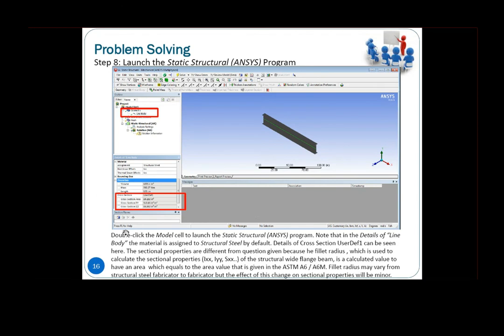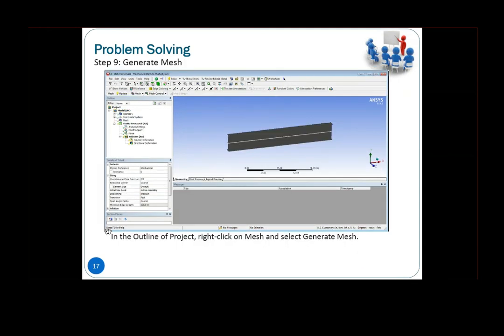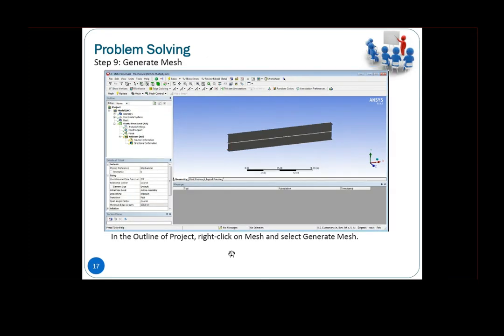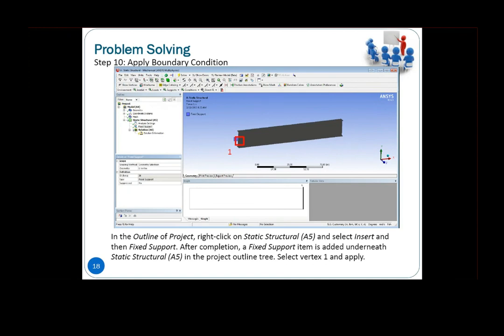All right, it's okay. Then we can do a meshing. Here again we want 2 nodes, 1 element, so we put a larger size in this case. So we have 2 nodes, right? Then here we insert the supports as well as the loads.